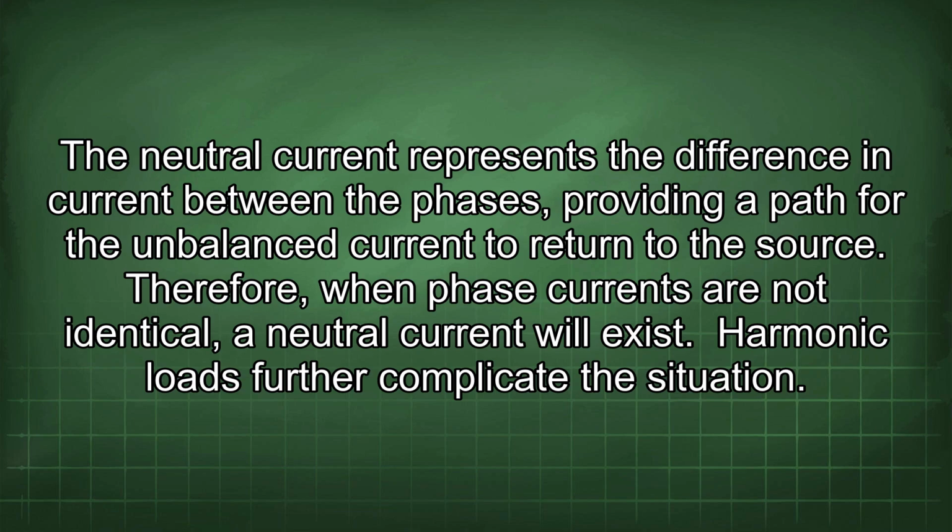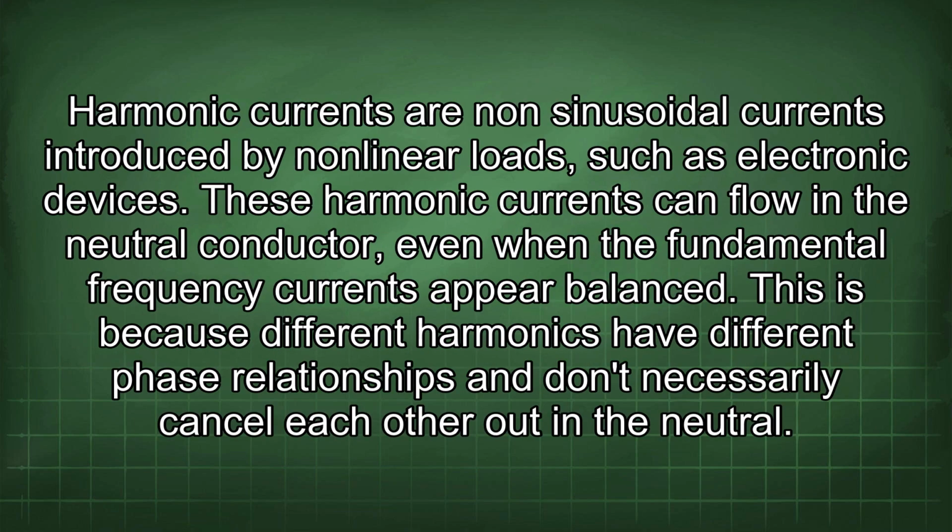Harmonic loads further complicate the situation. Harmonic currents are non-sinusoidal currents introduced by nonlinear loads, such as electronic devices. These harmonic currents can flow in the neutral conductor, even when the fundamental frequency currents appear balanced. This is because different harmonics have different phase relationships and don't necessarily cancel each other out in the neutral.